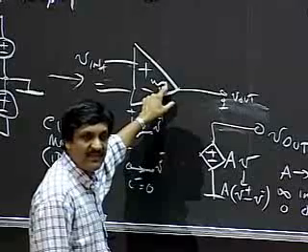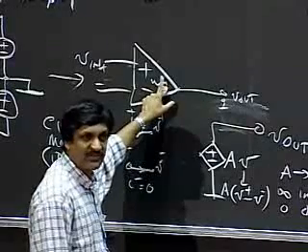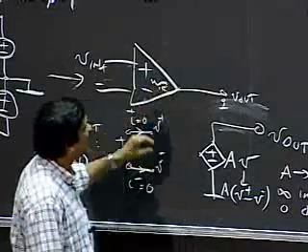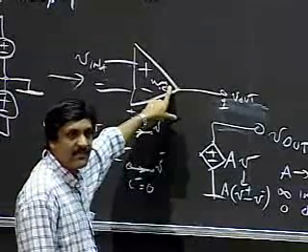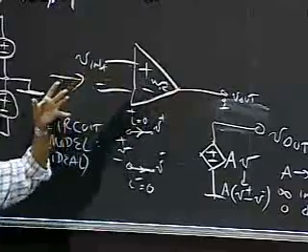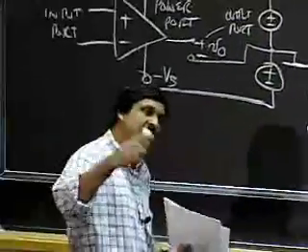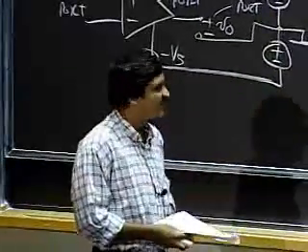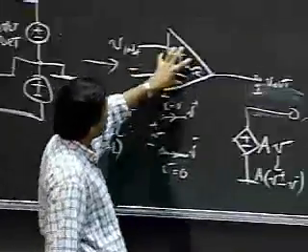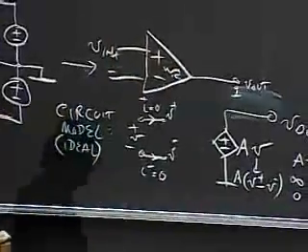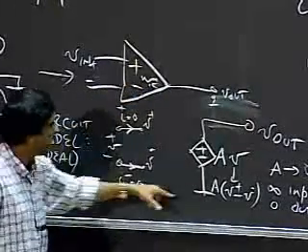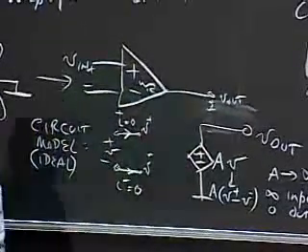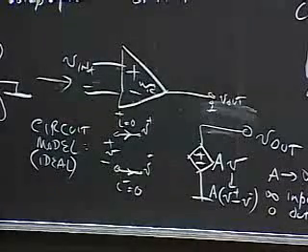You saw a variant of the source follower on your quiz as well in problem 2. So a circuit that looks like that appears at the output. Remember, for the source follower, the resistance looking in from the output was very, very small. So you have seen some of the pieces that go inside the amplifier, but we will deal with this as a building block and simply represent it using this little abstract circuit.